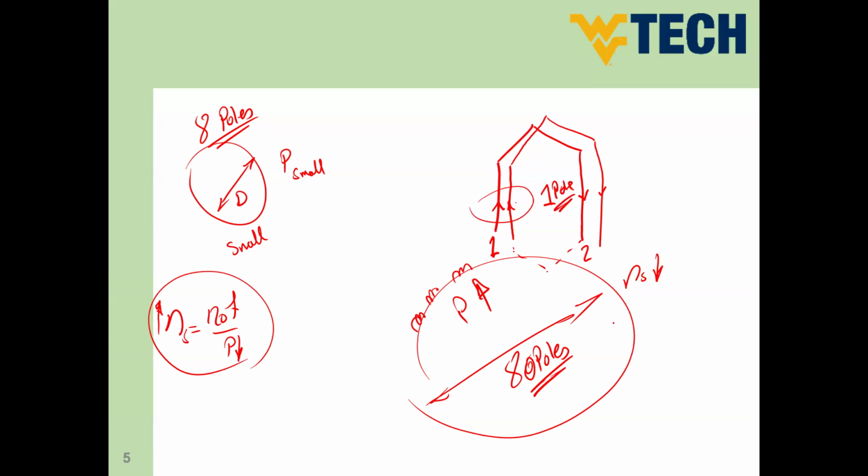So mainly we use the cylindrical type in high speed mechanical sources, like steam turbines and gas turbines. However, we use the salient pole in low speed machines, like in the case of wind turbines and hydraulic turbines. In this case, we prefer to use salient pole machines instead of the cylindrical type.